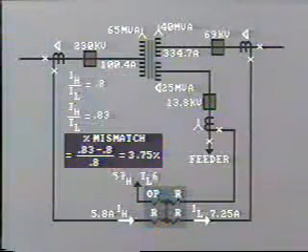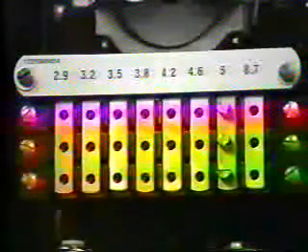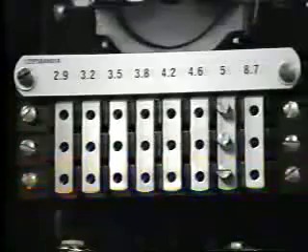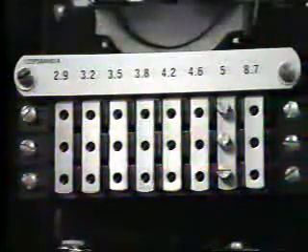At times, the mismatch may be too high for good reliability, even when using the whole range of taps. In this case, it may be necessary to use auxiliary CTs in the main CT secondary circuit.